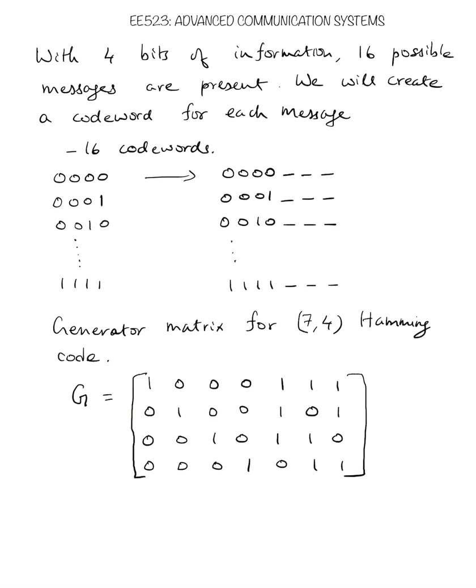We can multiply the message bits with the generator matrix only if the number of columns here and the number of rows in this are identical. So we have 4 columns in the message vector, and the generator matrix has 4 rows, and the generator matrix also has 7 columns because we need to produce a code word of length 7.